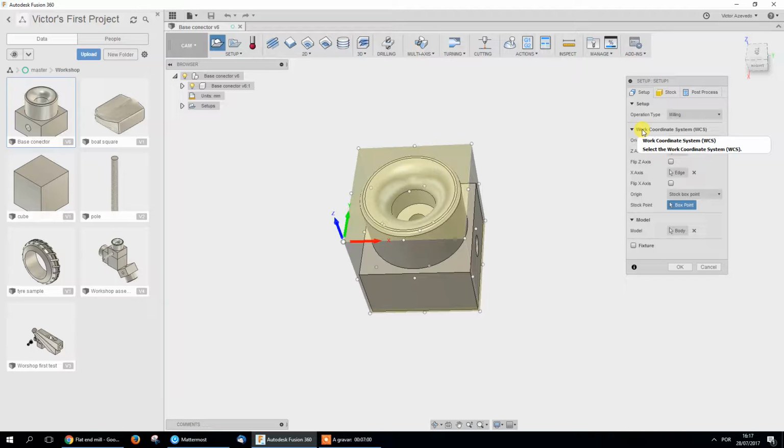So with my probe, I just come here, touch, and see the surface. It gives me the Z0 of my work. And then I can find the corner up here. And this is going to be my 0. In this case, if this is the block, the 0 will be made on this side.